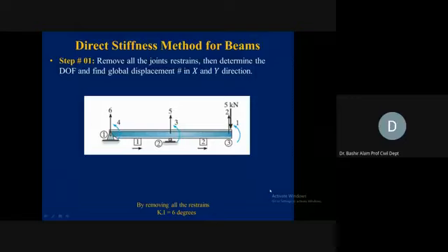Element 1 we say from joint 1 to 2 and element 2 from joint 2 to 3. Again, remember how this numbering is done. Free is given the preference followed by the restrained one, and the order is your choice. You have the flexibility for whatever you assume for the free and for the restrained one.